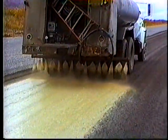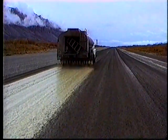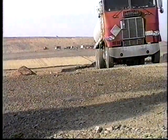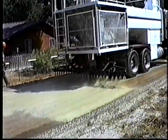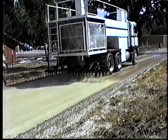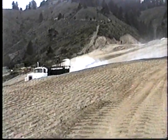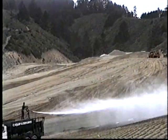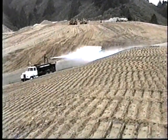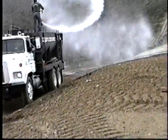While road oil is produced as a non-water soluble emulsion, which cures to provide permanent bonding, the emulsion is normally diluted with water in preparation for treatments which involve application to previously hardened or compacted surfaces. Dilution ratios vary according to project requirements. Let's take a brief look at use of the road oil resin modified emulsion for erosion control treatments. We are watching an application by a truck-mounted hydro-seeder unit, which is the preferred equipment for applications on steep slopes or areas where equipment cannot operate directly upon the surface to be treated.